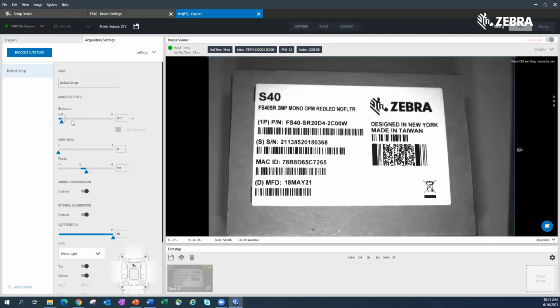Another adjustment that goes into effect is the digital I/O we talked about. Remember, GPIO 4 through GPIO 8 are digital I/Os. That means they pull the power from the camera to send the power out, right? So if I start activating all of those, you'll see this maximum red line start moving to the left, because I'm taking the power that was available for the light and using it somewhere else.